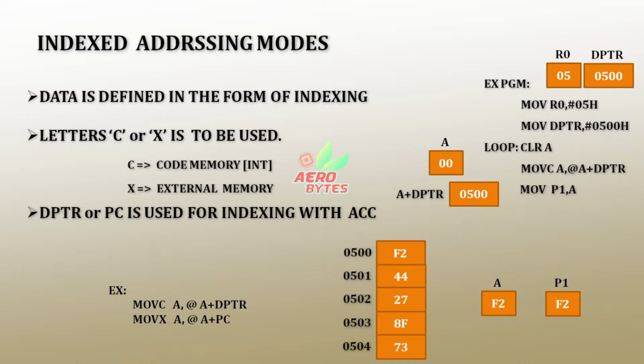This is the use of the application. We can index the data while processing, and the data comes one by one. Increment data pointer, meaning the data pointer content is incremented by 1. The data pointer content is 500, so 500 is incremented by 1. It is 501.